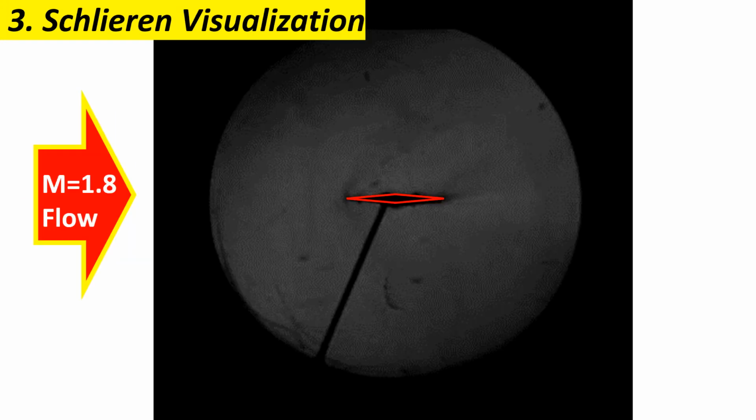Now it's time to see the Schlieren visualization. The flow is from left to right. This is the actual flow happening in the wind tunnel, and the aerofoil is indicated. We can now see the wake start to develop, so it's capturing the startup procedure of this wind tunnel. Now the valve is gradually being opened. The wake is developing. Now it's still not supersonic, and gradually the speed